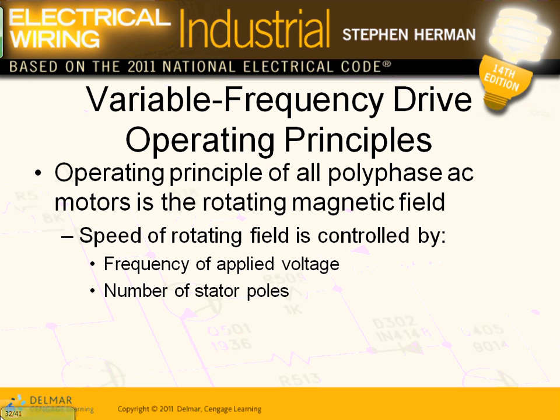What is a VFD? A VFD takes the AC to DC, controls the DC, then spits the DC out as some form of an AC across the motor. And in between, guys, when we get the DC, you can reduce the voltage, and then invert it at the right frequency and at the right voltage to control the speed. But it is outputting an AC. Some form of an AC pulsation. The output is an AC. Yeah, it's alternating, some form of a pulsation alternating AC. You're going to see pulse. You'll see there's a nice picture of it in a second here.